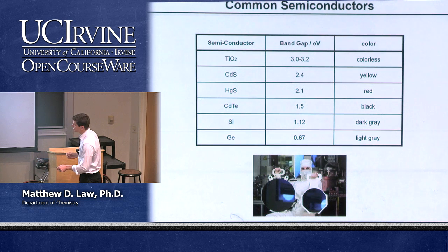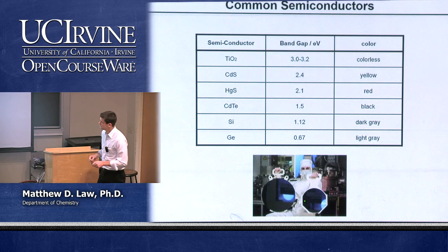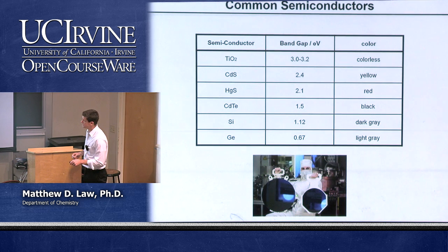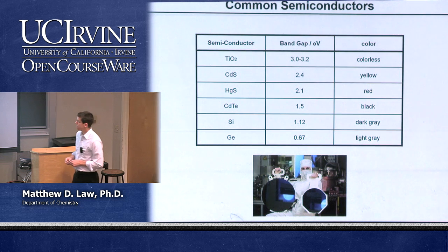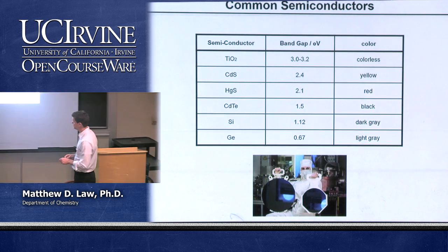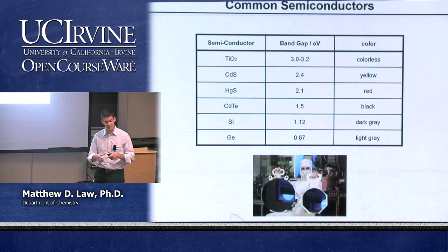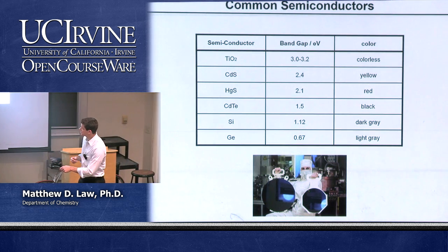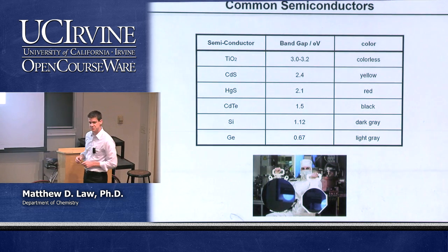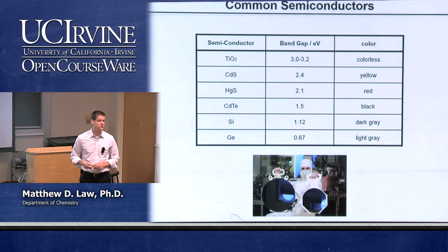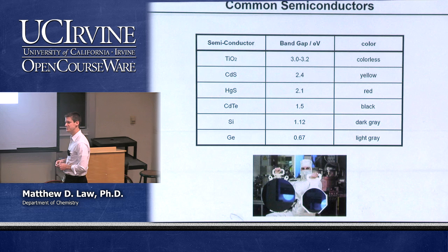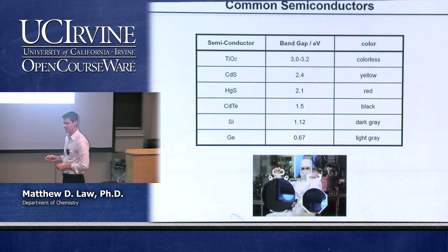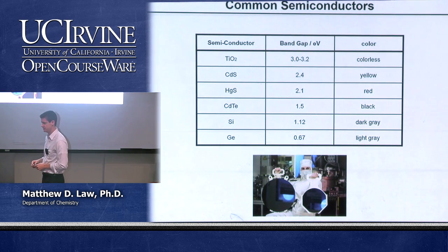And these are examples here of two different silicon wafers, okay, that integrated circuits are built on. This is a 12-inch wafer, and this is the new generation of 18-inch wafers. Right? My group uses a lot of silicon wafers in our research, and we use little baby 4-inch wafers. So these wafers here are actually quite astonishing. They are single crystals all the way across, and they are pure to like 1 part in 1 trillion or better. So there's pretty much only silicon atoms present in there. A little bit of oxygen, a little bit of carbon, and that's about it.